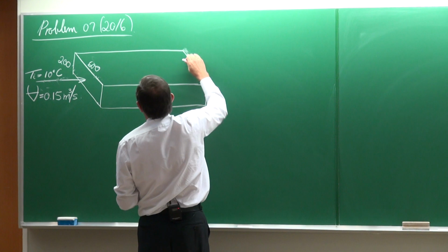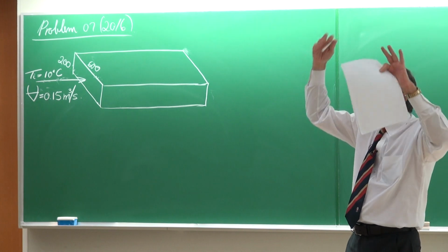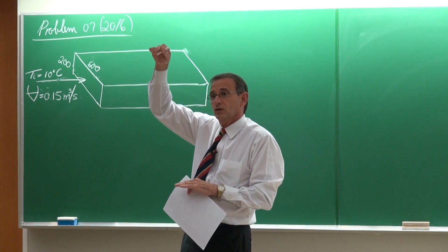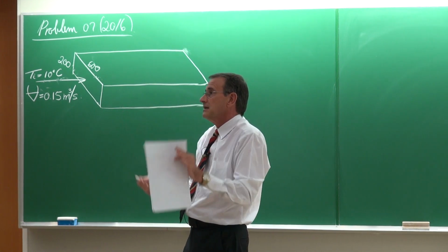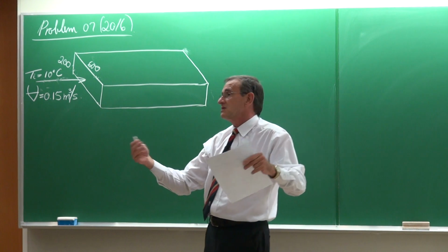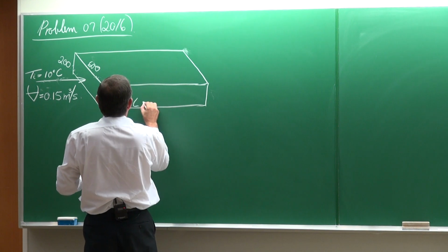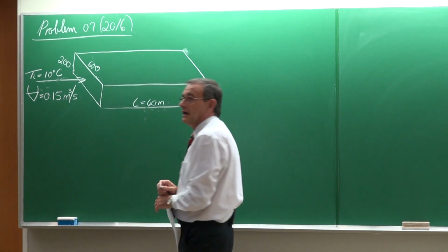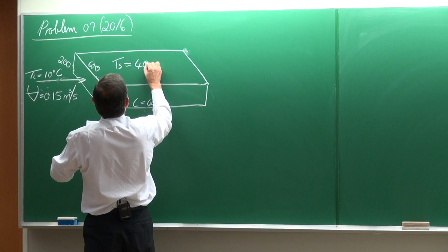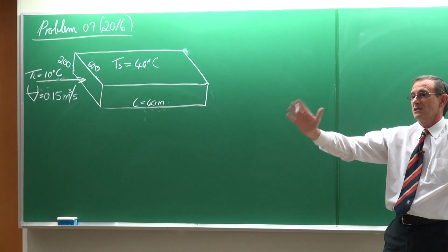Where will you get that? Well, you'll get it in buildings, in the attics, into the ceilings. And because it is in the upper parts of the building, all the hot air obviously rises and collects there. The temperature there can typically be 40 degrees Celsius, and in some cases even higher. So it is 40 meters in length, quite a long one. And around it, the air is at the temperature of 40 degrees Celsius. So we can assume that the duct surface temperature is 40 degrees Celsius everywhere.